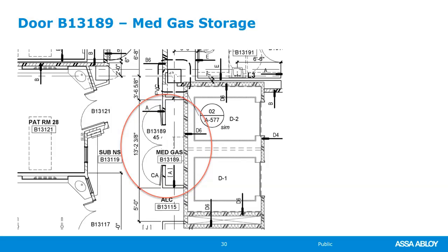because that meets code. However, if you recall from our code session, sometimes even though the building code, and we have multiple codes for this project, there were 4 different codes that this project had to fall under. And if there's any conflict between one or more codes, you have to go with the more restrictive requirement. All of the requirements in the codes permitted manual flush bolts and no door closer. But